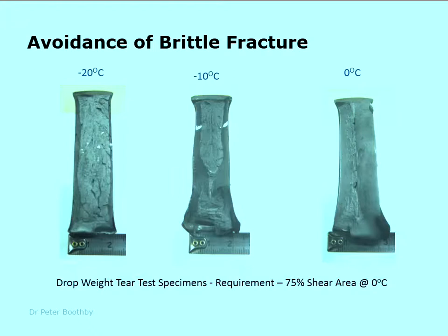However, because it's expensive and it can't easily be applied to pipelines less than 12-inch diameter, in many cases the Charpy test is used, and the Charpy test really is used to ensure that at the design conditions of the pipeline you are operating on the upper shelf of the material. And they're just some pictures of typical Charpy impact.